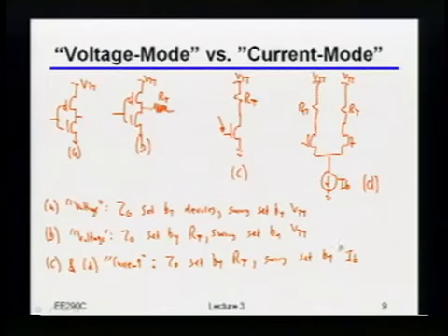Okay, so now I'm just going to put this bias current sort of in parentheses because it's not quite as immediately obvious what I mean by bias current in that particular case, but you can imagine I can sort of arrange the gate voltage so that it's a mirror or something and it sort of looks like a bias current. Just, I don't know, wave your hands furiously and hopefully you'll see it. Okay? So what I really mean, of course, by both of these, or really to have both of these things happen, that does say the devices have to stay in saturation.